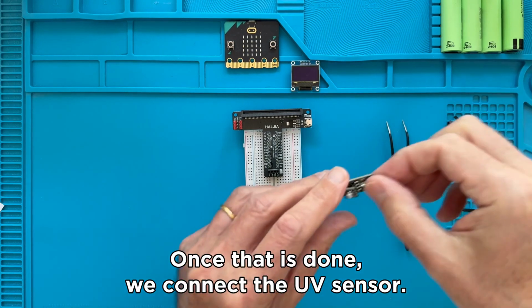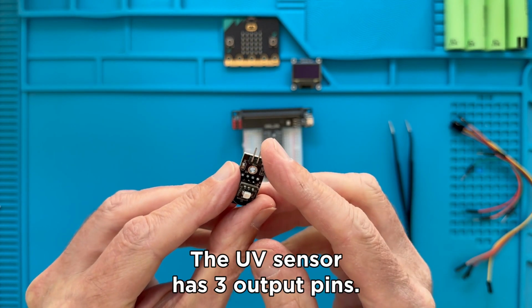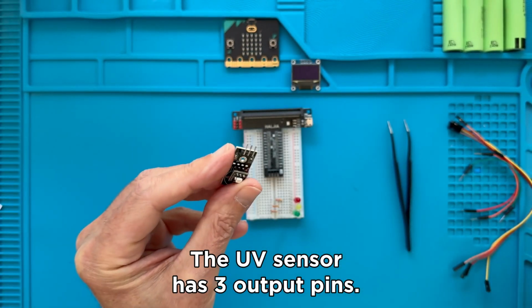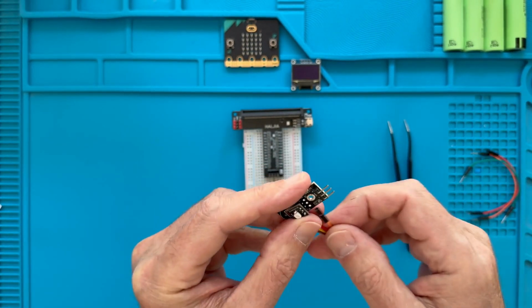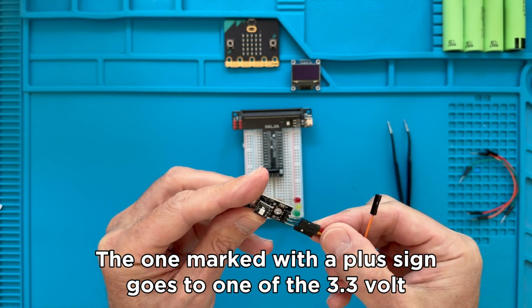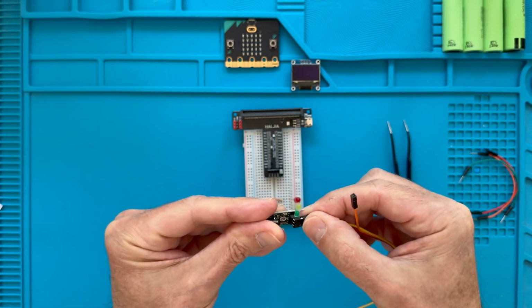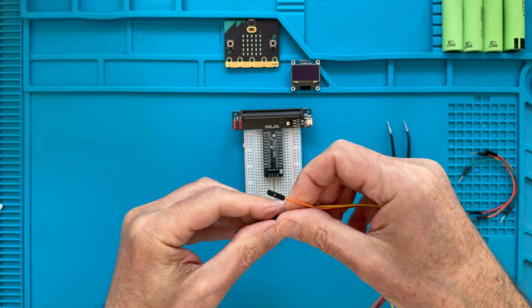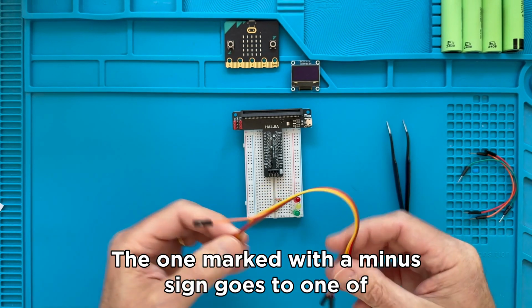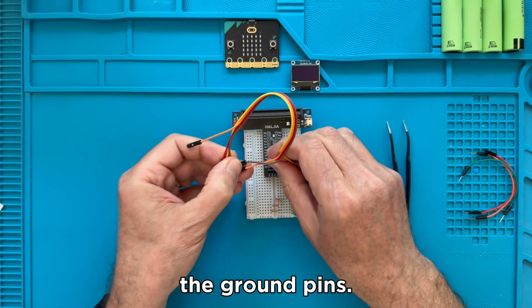Once that is done, we connect the UV sensor, and the UV sensor has 3 output pins. The one marked with a plus sign goes to one of the 3.3 volt pins on our microbit. The one marked with a minus sign goes to one of the ground pins.